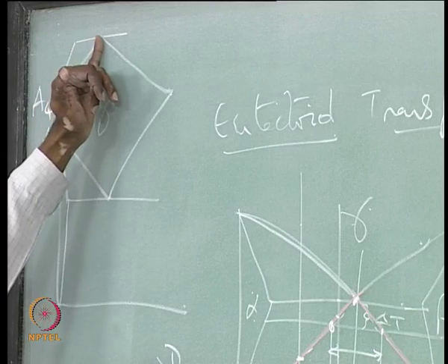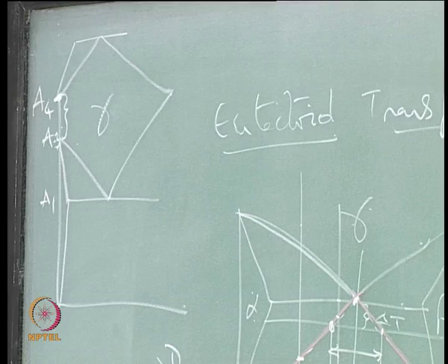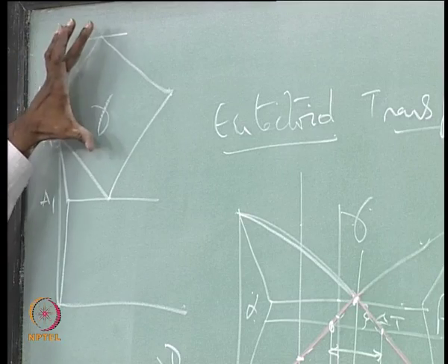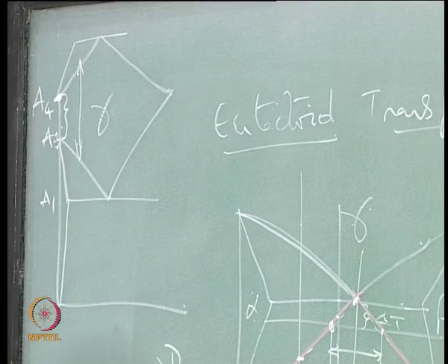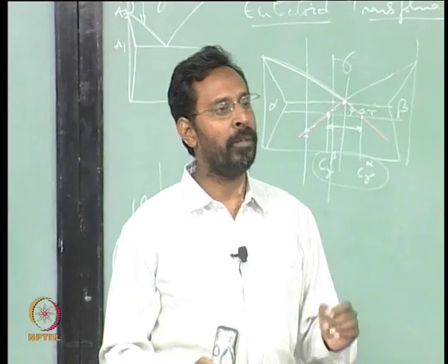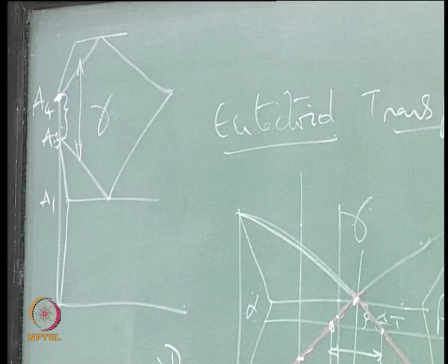Of course this is 0.18, this is 0.8, so there is a difference. So there is a scale difference. So as I know that these two are increasing, that tells you this field is increasing, and that means whenever the phase field expands, that particular element stabilizes that structure. This is basically because the carbon wants to be in an FCC structure rather than in a BCC structure.